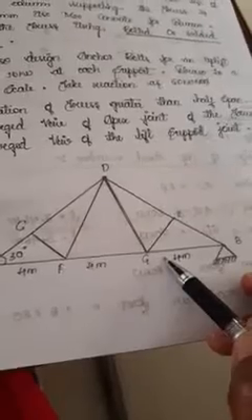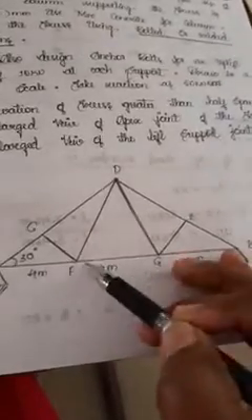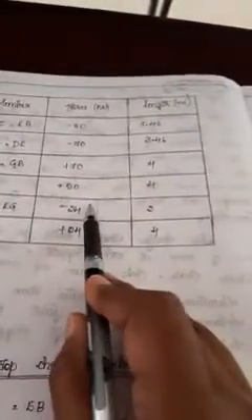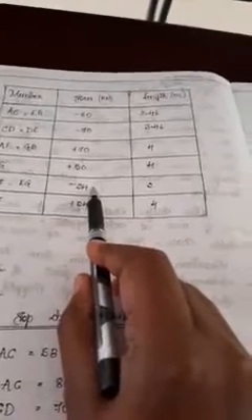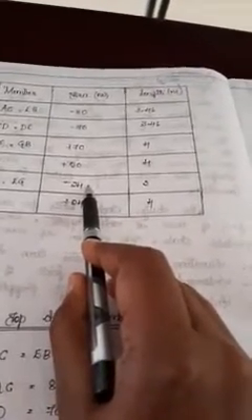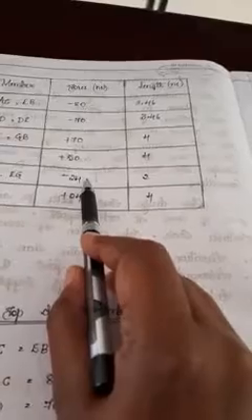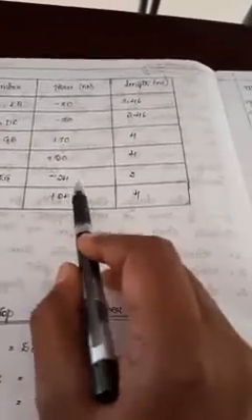CF and EG are both inner chord members, and FD and DG are also inner chord members. The values given are minus 24 for CF and EG, and plus 24 for DF. It means one is a tension force and the other is a compression force. Because both values are the same, you need to design the inner chord member for the tension force as well as for the compression force.